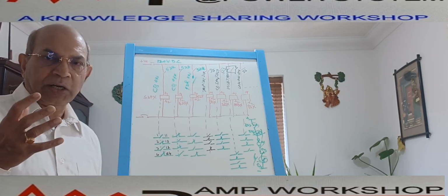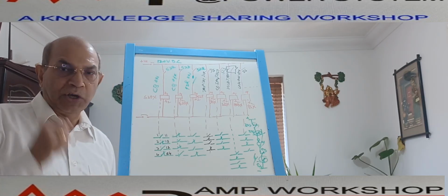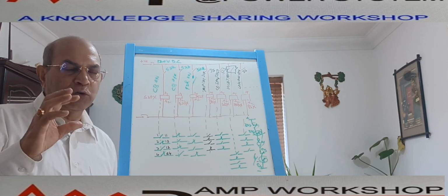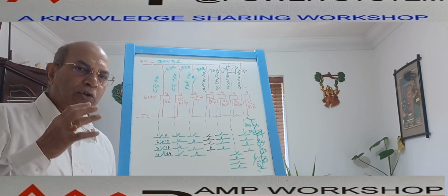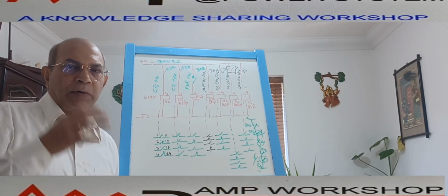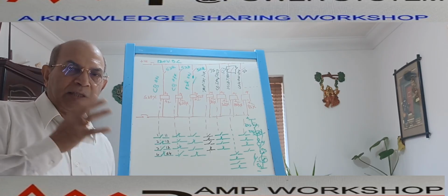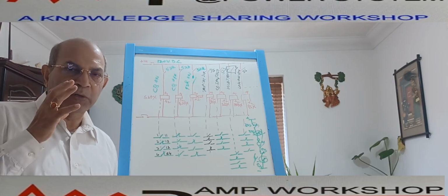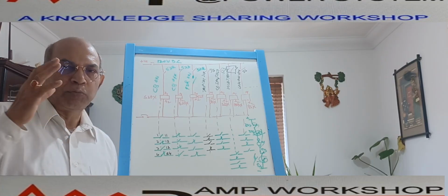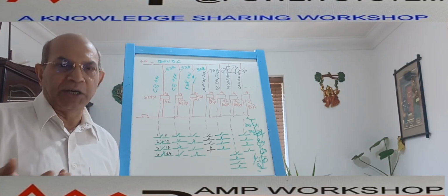Now in a complicated circuit with multiple utilization, suppose this signal is used in different locations. For example, the trip circuit supervision relay has 2 NO 2 NC contacts. Suppose you want to supervise the trip coil position from the switchgear, from the control room, from the DCS, from a remote station somewhere. We have seen the trip circuit supervision relay is normally energized. When the trip circuit is healthy, this relay is energized, so the NO contact is used for the remote indication. So we have only 2 NO contacts. If we need more NO contacts, how will we get them?